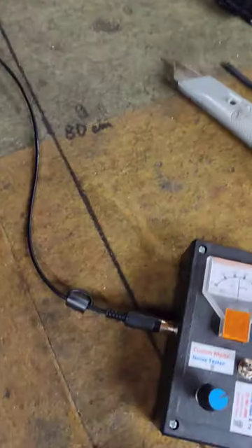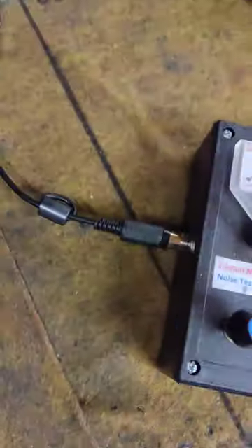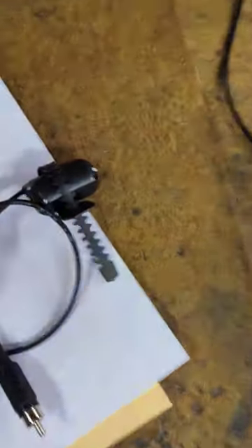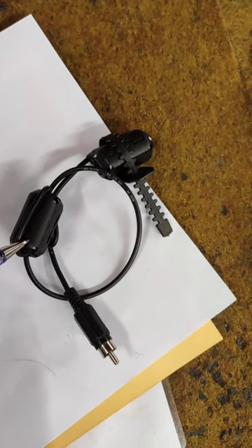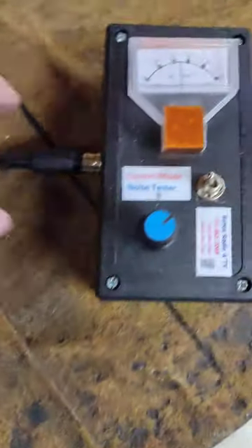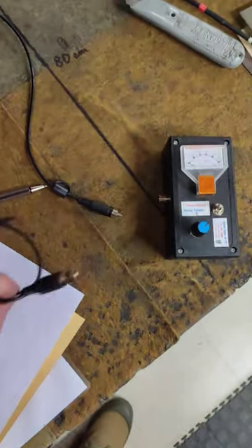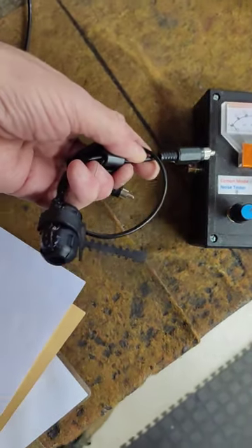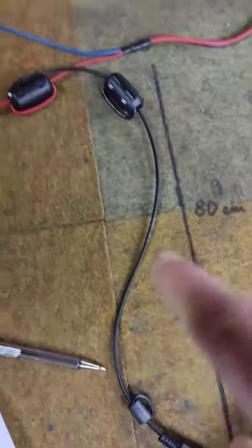And the beautiful thing about this common mode tester is, let me just get another sort of sensor. Just by changing the actual different sort of probe, I can use it for coaxial cables to measure common mode in antenna systems, or by plugging in another sensor, I can actually measure the common mode noise in power supplies and wiring.